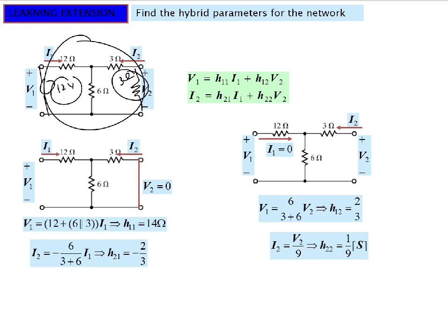So what will we do? We will use the Z parameters, because that thing is straightforward. We find Z11, Z12, Z21, Z22, and then we find the relation. We put values of voltage and impedance on input and output side respectively.